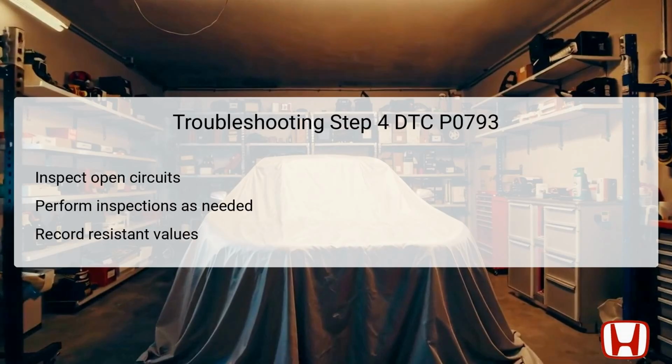The troubleshooting workflow continues with an inspection of potential open circuits, which involves conducting detailed resistance tests on the appropriate wires. Technicians should focus on verifying that the resistance levels meet specified parameters, which should generally show less than 1 ohm for intact wires. Detailed inspections should be performed as dictated by the preliminary test results. If none of the wires displays proper voltage or resistance characteristics, it indicates a circuit failure.